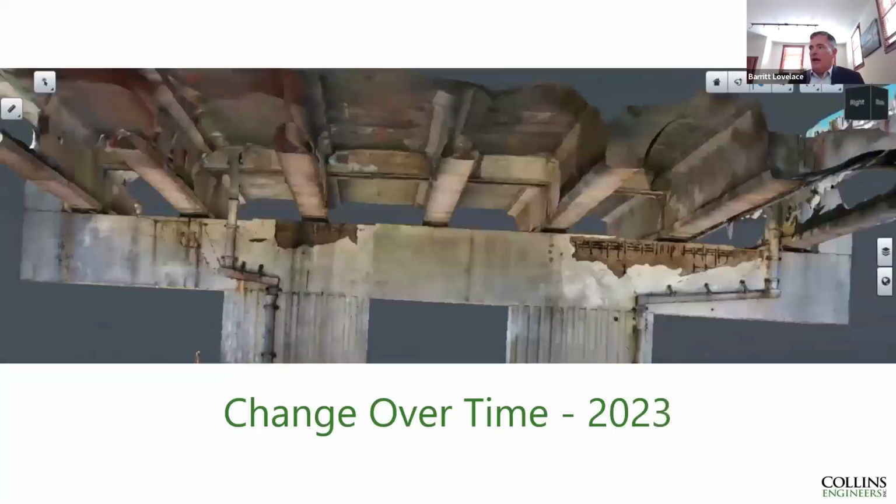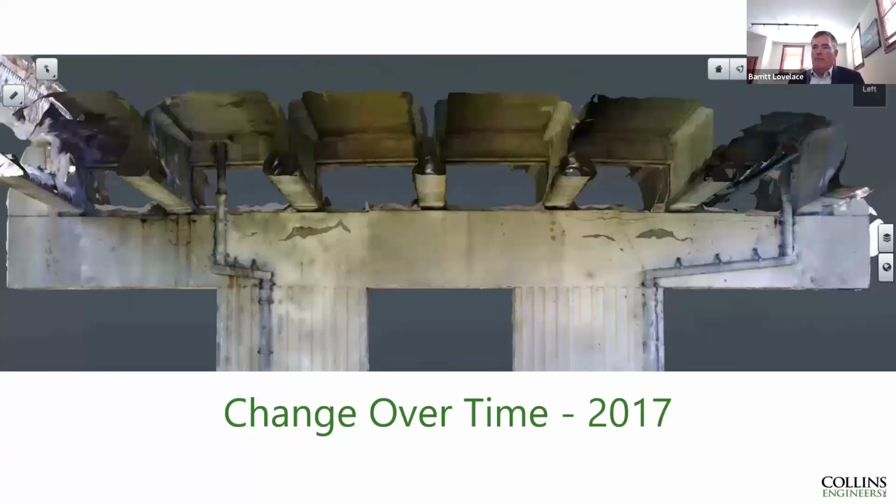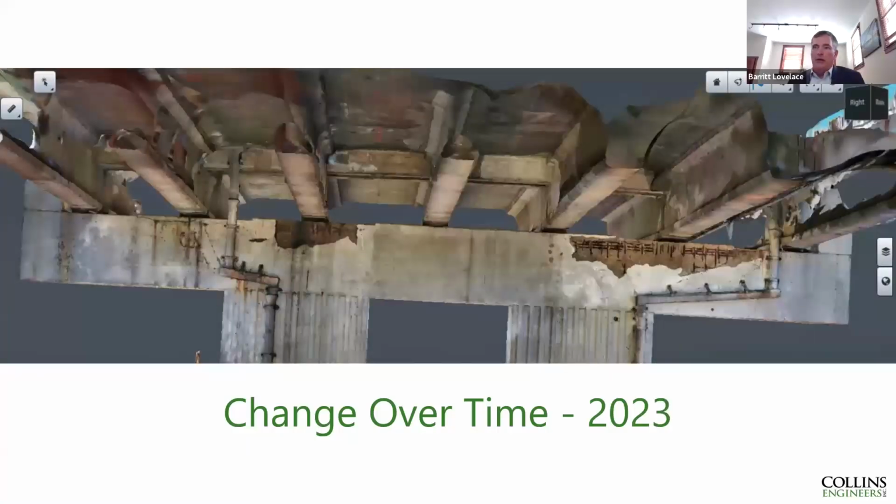And in this case, we had an inspection time of about 6 years, so we could really see how much has changed over that time, and really be able to measure how these concrete spalls have changed, and how the concrete cracking may have changed over time. And that's something that, again, is difficult to do in a traditional manner, and we can do it with the digital twins much more accurately and be much more confident that something is actually changing, or maybe it's not changing.